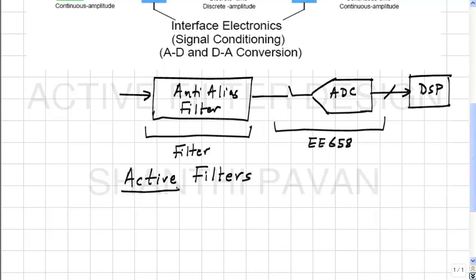Okay. So in other words, a filter which is very discriminatory in nature requires, as I'll give you intuition later on, poles whose quality factors are very, very high. And once the quality factor is very high, it turns out that you cannot do it with simply either RC or RL. You need both kinds of elements, both capacitors as well as inductors, in order to realize filter transfer functions which exhibit high degrees of rejection. If the filter is very loose, then most likely in many applications it may not even be useful.